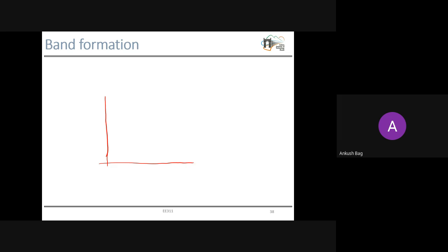So this is T and this is your carrier concentration, maybe electron or hole. First we will discuss the intrinsic semiconductor, the semiconductor without any doping, a pure semiconductor. If we start from 0 Kelvin, there is no thermal energy to break any covalent bond, so there will be no carriers at 0 Kelvin.